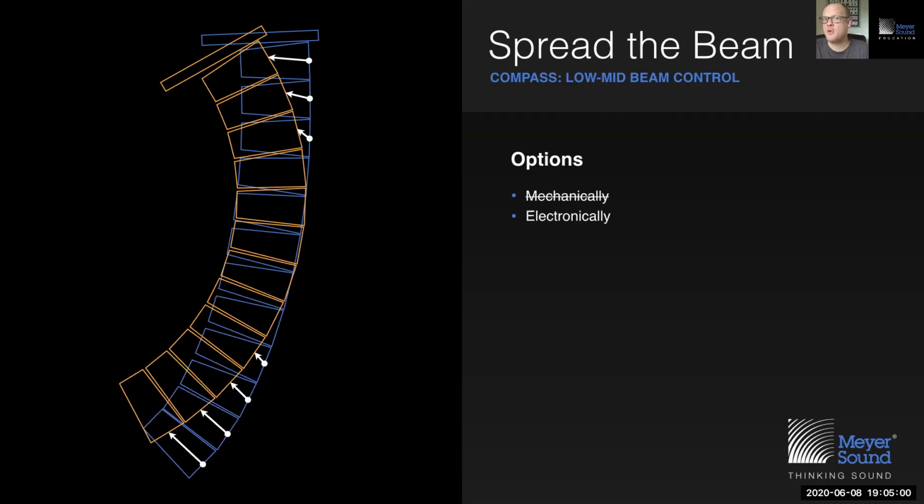Now, if we were to do this with pure delay, by which I mean electronic delay applied to each loudspeaker for all frequencies, then that's the last time that they will let you try doing that. Because if you start to delay loudspeakers individually within a line array, you're setting the table for shed loads of things to go wrong.